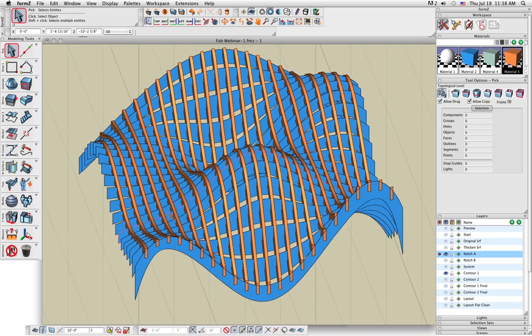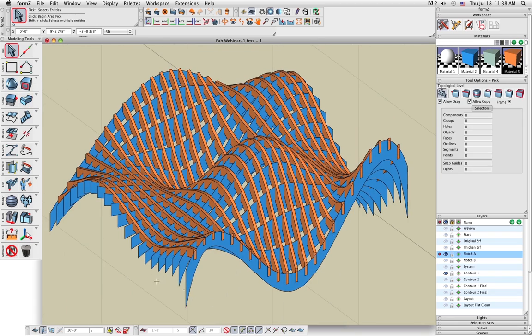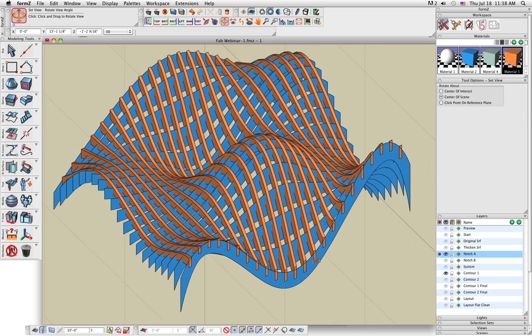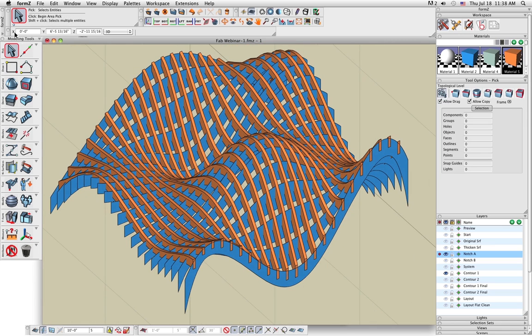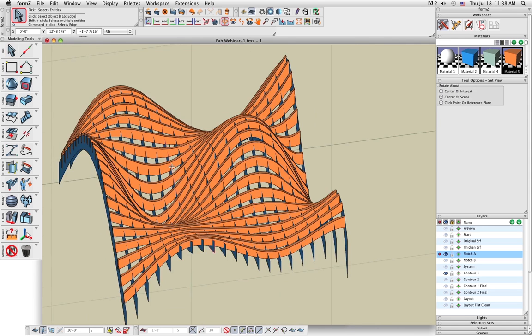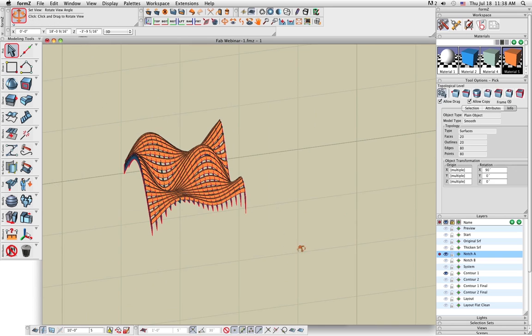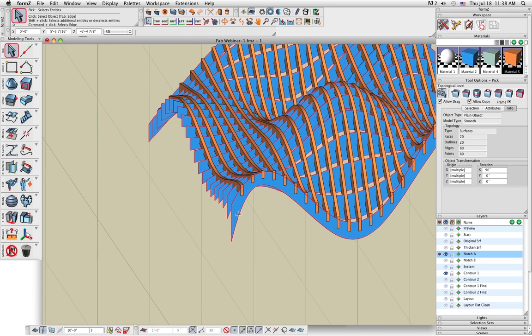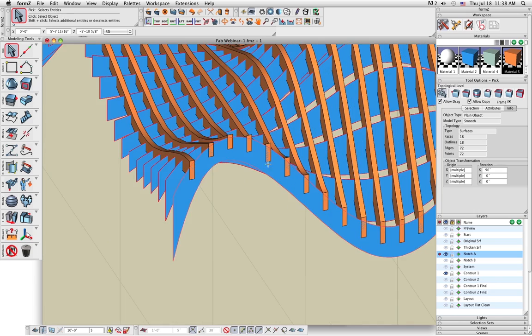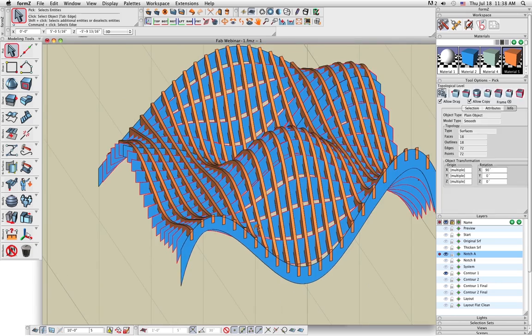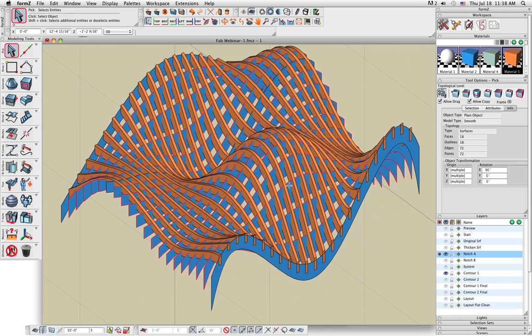So what we're going to do now is split our contour 1 using our notch A contours that now have thicknesses to them. So I'm going to select all my blue contours, which is my contour 1. I'm going to deselect the first and the last, because we don't need to cut the notches into the first or the last, because those would be our end pieces.